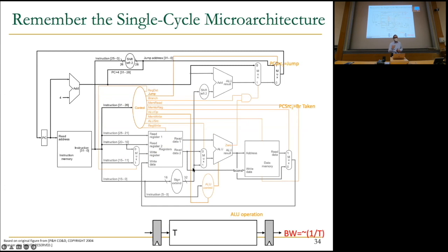And we're going to start with a single cycle microarchitecture, actually. It turns out single cycle microarchitecture is a better place to start for pipelining a machine than a multi-cycle, because multi-cycle reduces the resources significantly. Whereas in a pipeline machine, if you think about it, in a single cycle microarchitecture you need to use all parts of the machine in a single cycle, right? Because in a worst case, an instruction needs to go through all parts of the machine. Here, in a pipeline machine, you're really using all parts of the machine in a single cycle, except different instructions are in different parts of the machine, right? That's why it resembles a single cycle machine more than a multi-cycle machine, because in a multi-cycle machine, in a given cycle, you're using only a fraction of the resources.